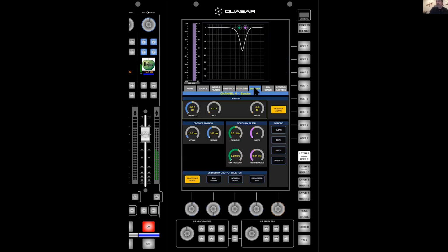On the mic side, though, we've got a world-class de-esser. And my favorite thing about this de-esser is it's an old school style of de-esser where you're going to control it by ear. And by that, you've got these 4 patch points down here at the bottom that allow you to listen to how the de-esser is working in real time. And so what we do is we extract the S out of the signal, we process the S, and we put the S back in. And we can listen to all of those patch points, the process signal, just the S, the signal without the S, or the whole thing together as a fully put together sound. So you can really dial in the right sound for your operators and really make it sound sweet.